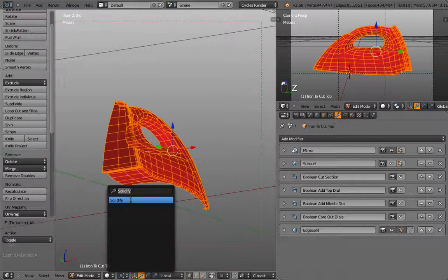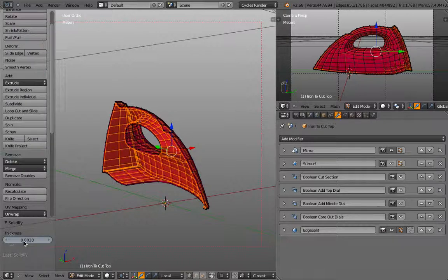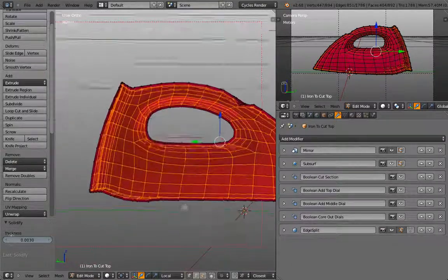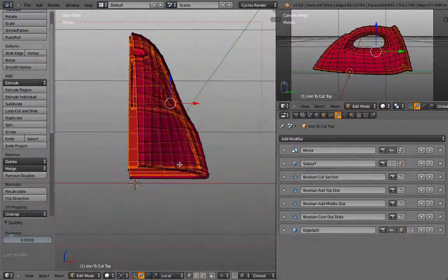So I select it, and then 3 millimeters, this is symmetric, is 1 meter, 10 centimeters, 1 centimeter, millimeters. So 3 millimeters would be 0.003. And there we see now I have this mesh created.